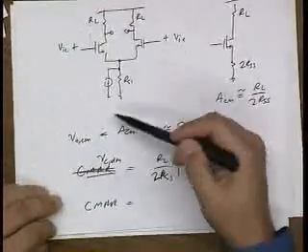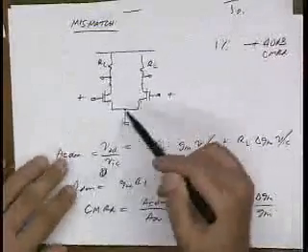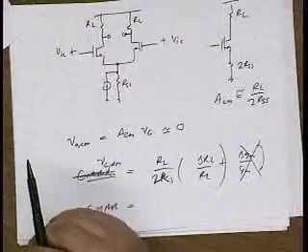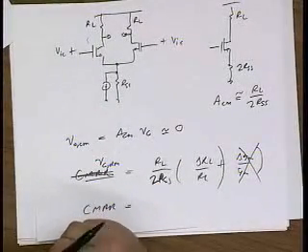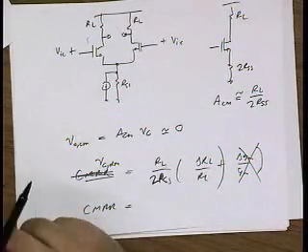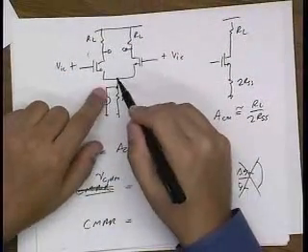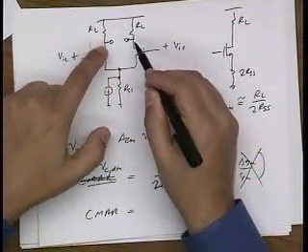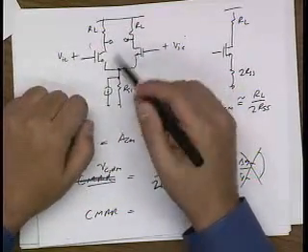So, does this current source contribute noise compared to this guy? Should we be worried about the noise of this current source? Okay. Lee, you're shaking your head. Why not? Because noise is a common mode signal. Okay, good point. If this is a fully balanced circuit, the noise comes here, sees the same impedance going left, going right, and so it goes into the output and it creates a common mode signal. So if we're designing a differential signal, great, I don't have to worry about the noise.